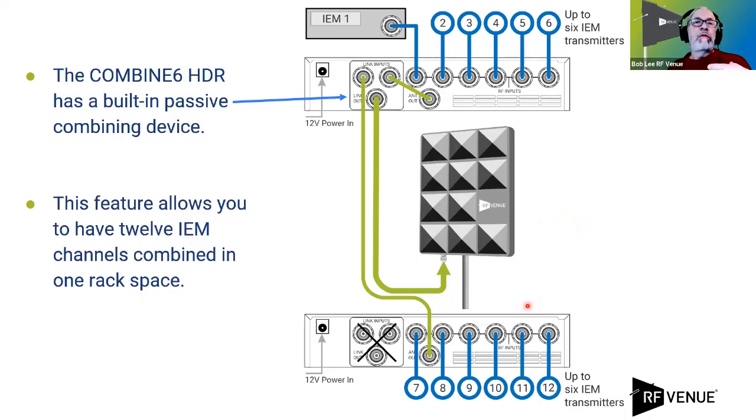But understand that you don't have to use multiple antennas for multiple in-ear monitor systems. In fact, it's better to not use multiple antennas and just combine everything down to a single antenna.